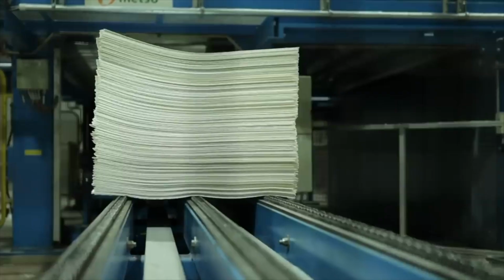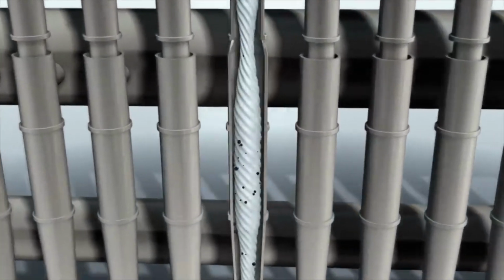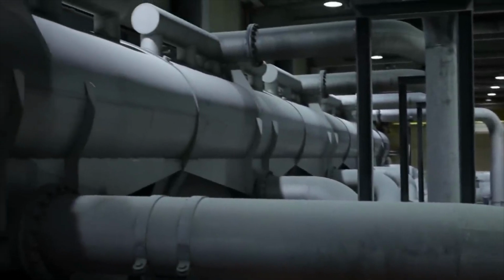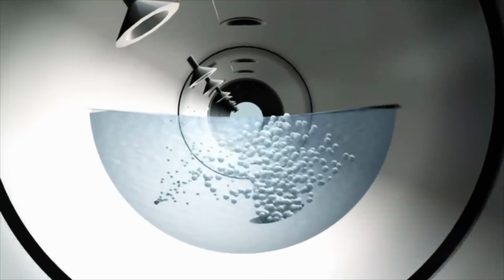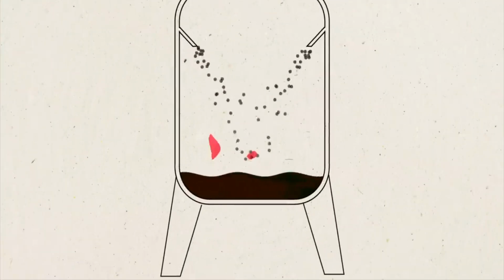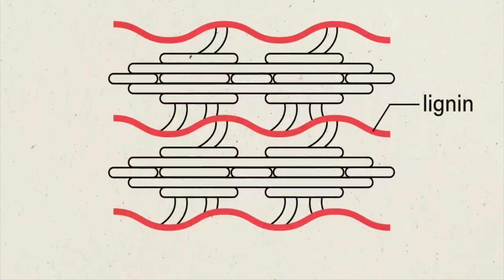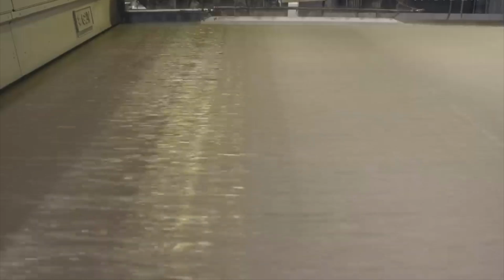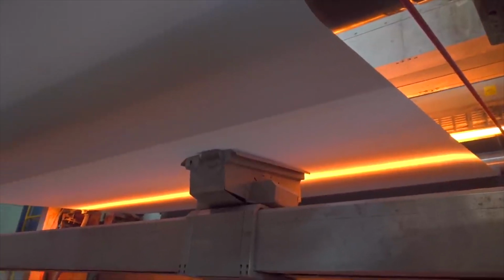Whether it is pulp from newer trees or recycled fiber, both undergo a pulping process to further separate the fibers needed to make paper. Mechanical pulping uses grinding devices and equipment to physically tear apart the fiber connections through intense mechanical action. Chemical pulping involves cooking the wood chips or recycled papers in chemical solutions to dissolve away binding materials, like lignin, and leave freer cellulose fibers available. The pulping method utilized depends on the paper product's quality needs and intended applications. Both processes result in paper pulp with increased fiber availability, ready for the next steps of paper formation.